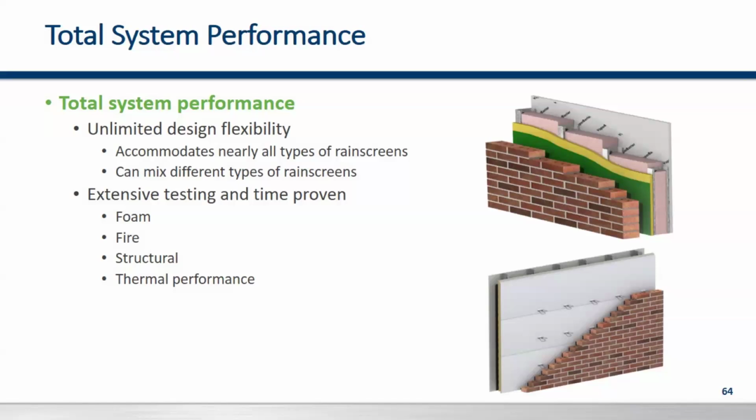The insulated metal panels, like I said, have been around for about 60 years. And while the concept of the panels hasn't changed much, certainly the materials and components have. When it comes to applicable fire standards, FM 4880, NFPA 285, ASTM E84, the IMP panels are Class 1, Class A panels. And when you look at the single skin materials, the single skin would all be non-combustible.